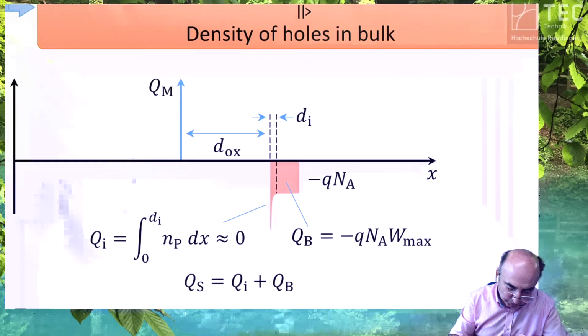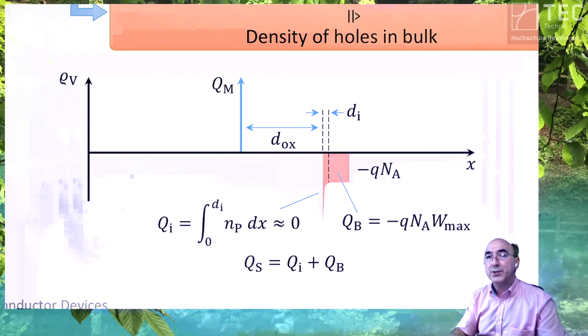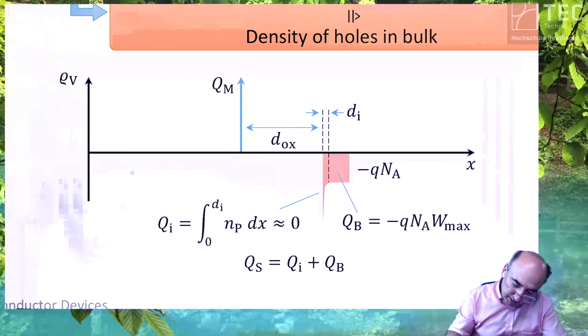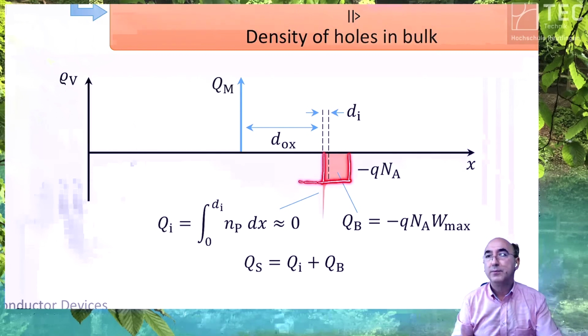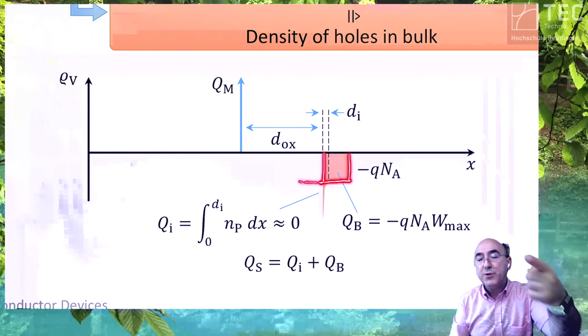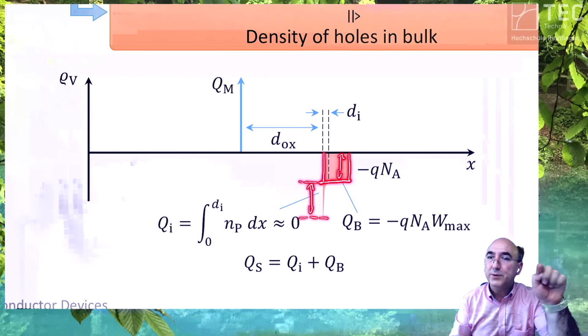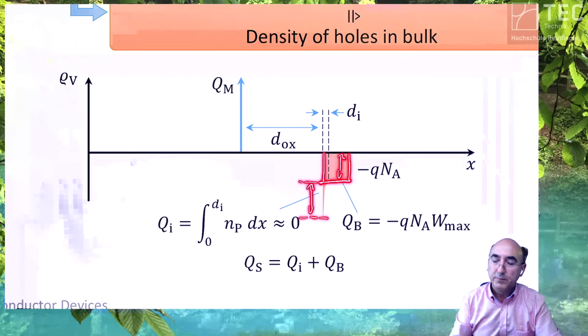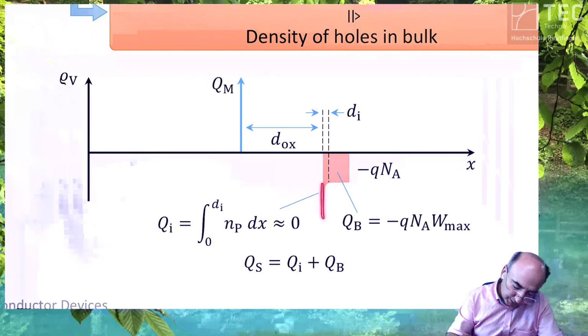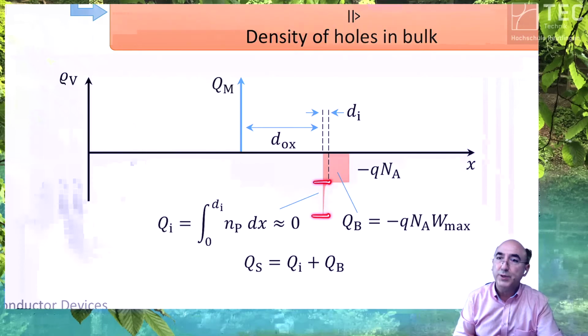And this means now the following. Now let's go to the charges. Your space charge has a certain concentration, okay? And your inversion charge has the same concentration on top. Therefore, this value is defined as the strong inversion.